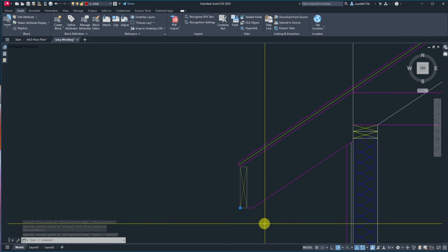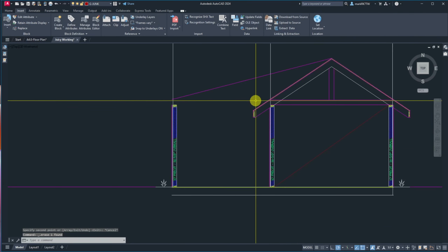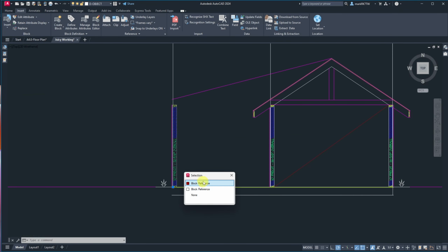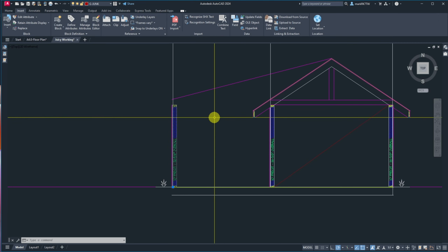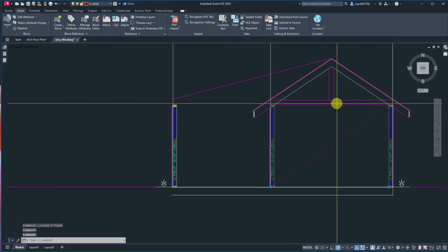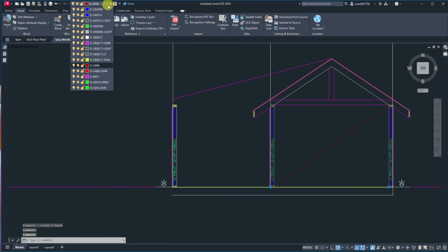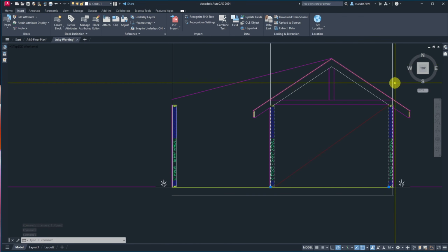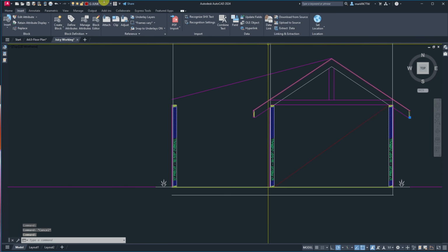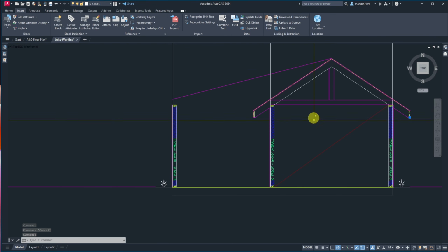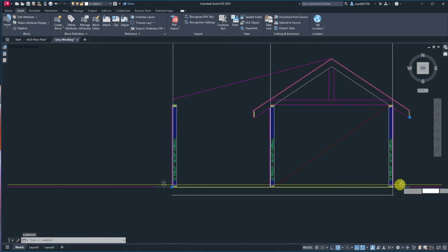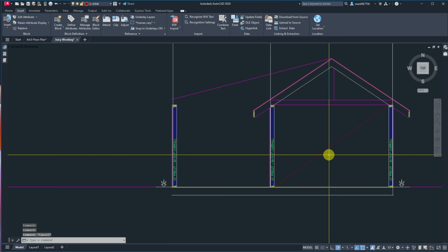One should be on the junk layer, which I don't need on this because the section it is going to print like this. Then I should have brought over an extra junk layer block. Now that is also in the junk. That one's on the junk. Now we're in the section drawing. So I want these to be printing over on this side of the paper. So that also, I want that to print. So now my blocks, except for these guys. Oh, no, they're fine. They're on the right layer.